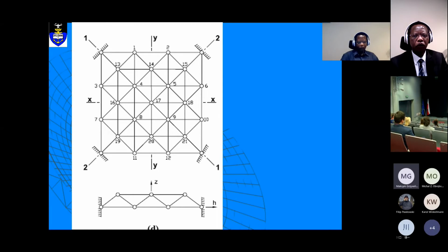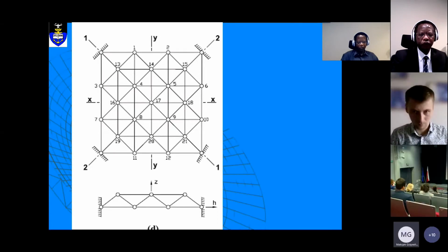Applying the idempotence of the symmetry groups in accordance with the procedure explained earlier, we reduce the vector space of each problem to a number of subspaces spanned by basis vectors in the form of symmetry adapted freedoms. Here are the results of the decomposition.